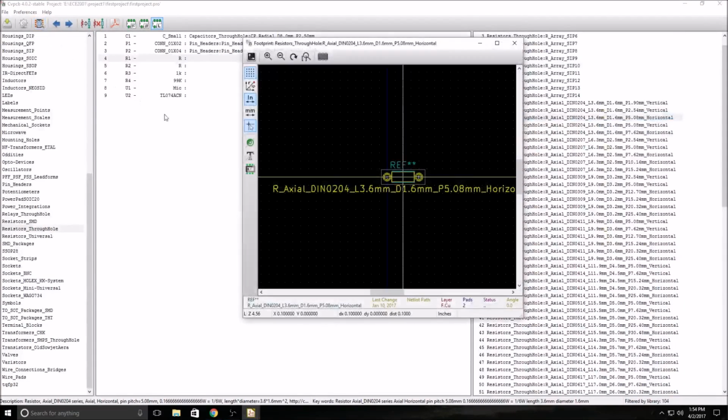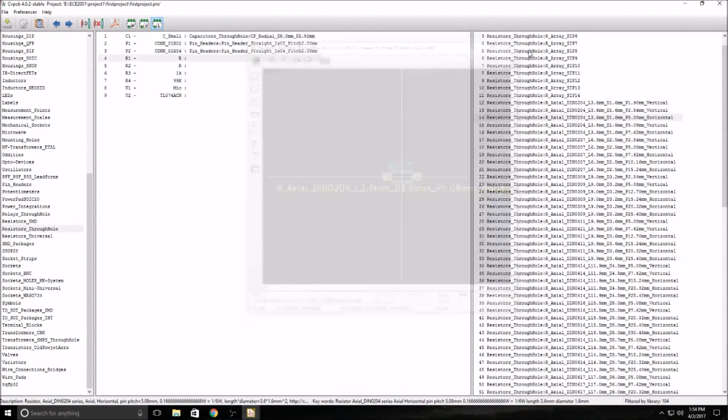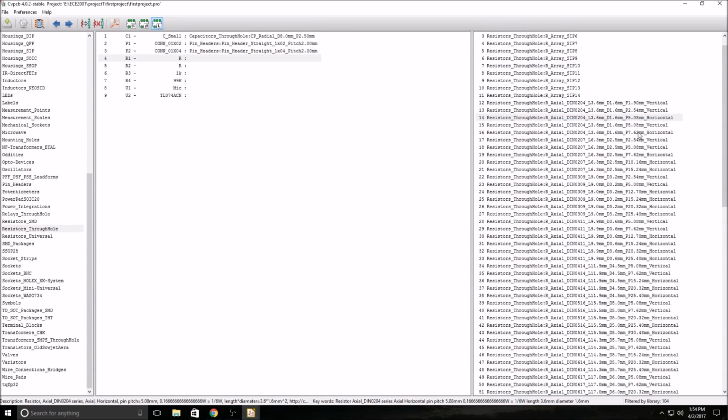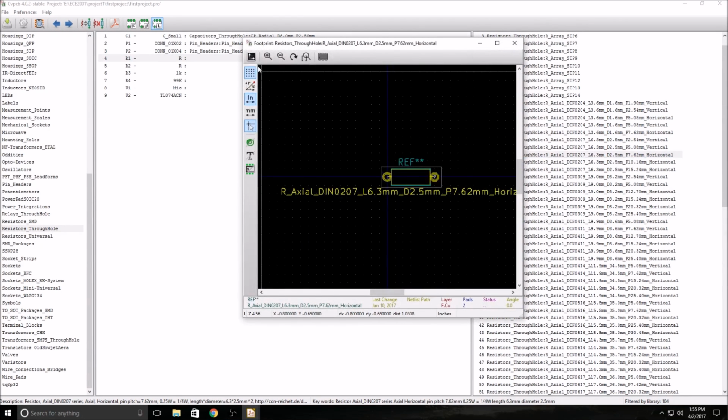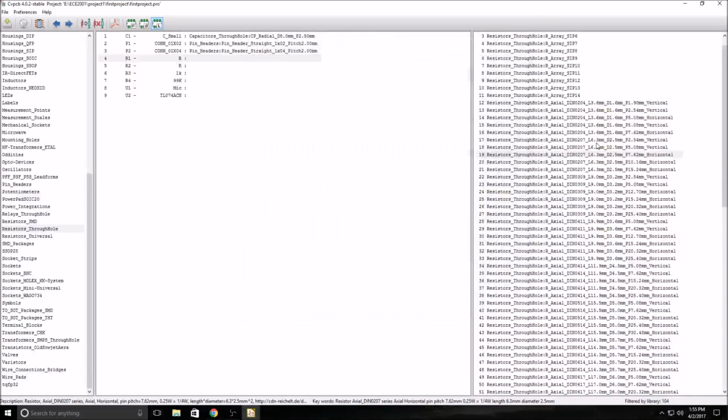Let's take a look. Is this the right one? Yep, we can use this one. Actually, we'll get a little bit more space because I think most of these are a little bit bigger. This length is 3.6 millimeters. Actually, we want to use a longer one, so we want a horizontal length of at least 6.3 millimeters. So we want to use this one. We can look at that. It fits most quarter watt resistors pretty well. So we need to add 2 of those.